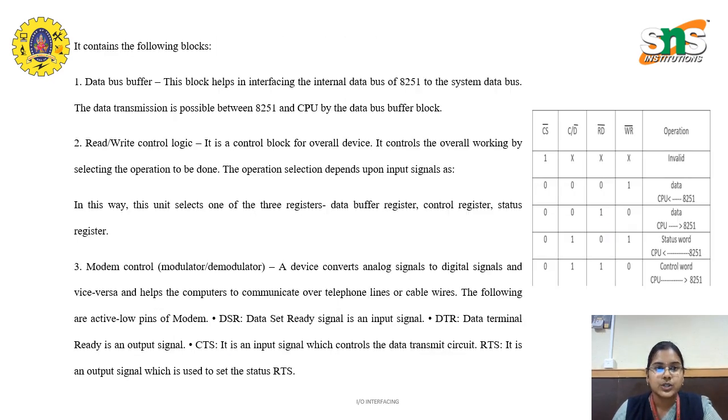In this architecture, first we will discuss the data bus buffer. This block helps in interfacing the internal bus of 8251 to the system data bus. The data transmission is possible between the 8251 and CPU by the data bus buffer block.